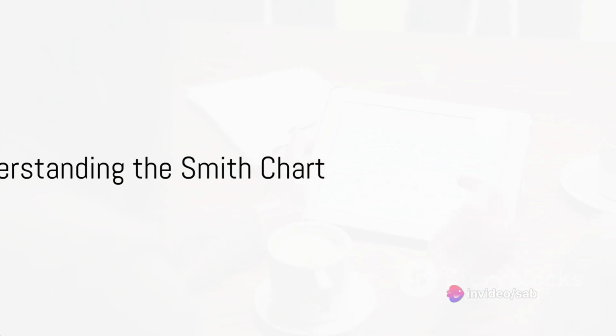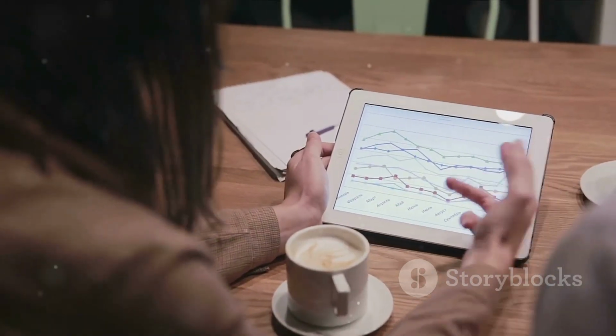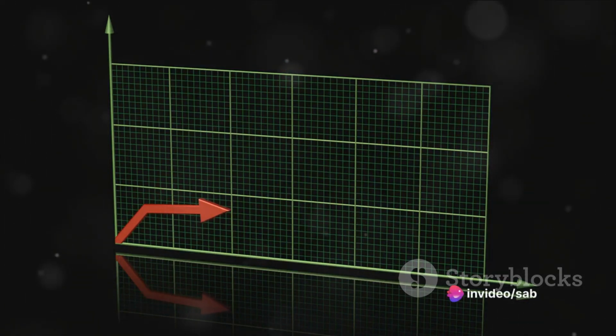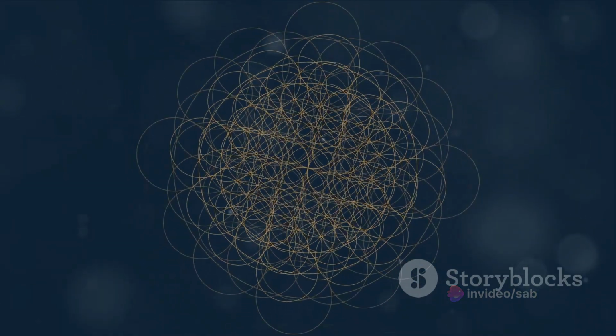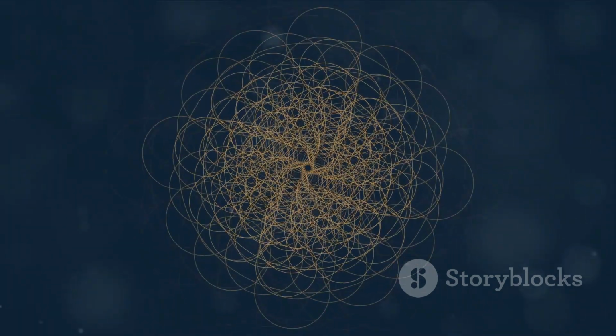Imagine a polar plot. This is what the Smith chart essentially is, a complex impedance plane. It sports two axes, a real or horizontal axis representing resistance, and an imaginary or vertical axis representing reactance. The chart is usually carved into concentric circles denoting constant resistance values and radial lines indicating constant reactance values.